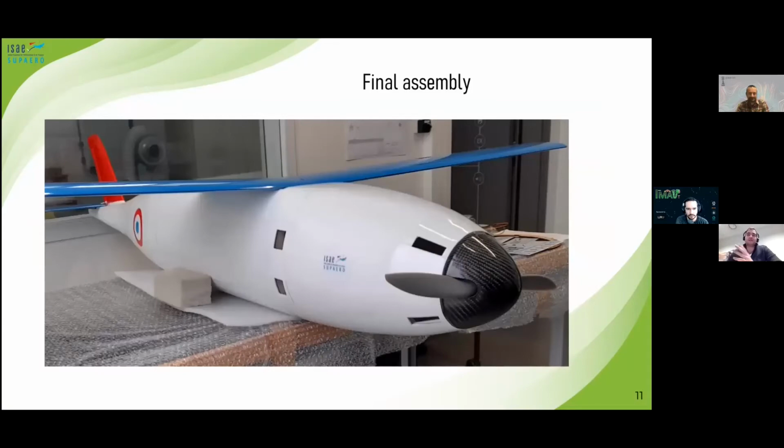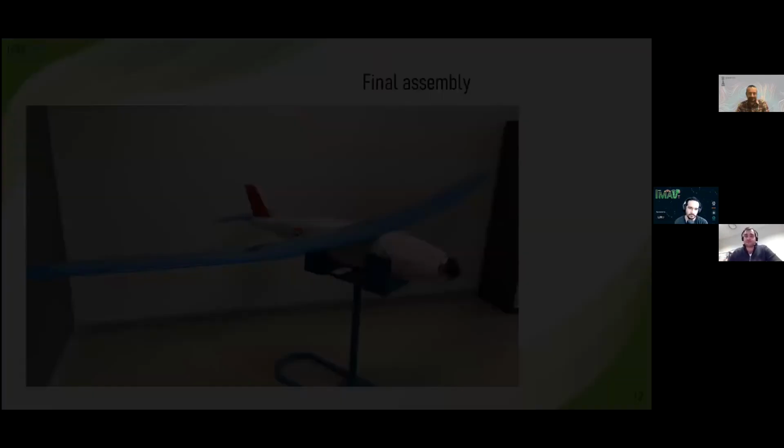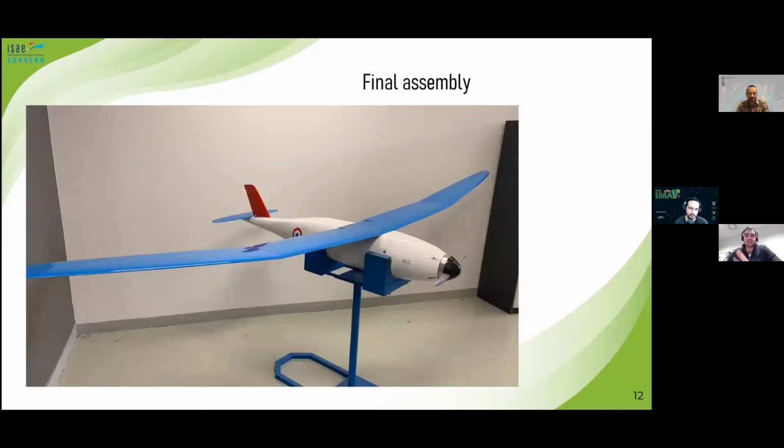So here is a preliminary, this is actually a final assembly. What you see here are the holes which are missing to be filled with 3D printed inlets and outlets. And you can see also, I will talk a bit later about that, the propeller has been integrated in the cone, and what you actually get when you integrate the propeller in the cone. You can see here the final assembly with the disc, with the now glued positioned inlets, a certain configuration of NACA inlets and outlets, with a complete wingspan of around 4 meters.